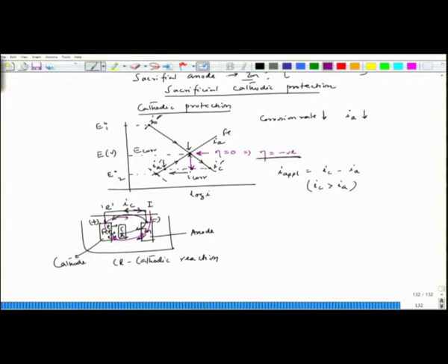Like that way, current will flow like this all the time, and then the entire surface of the metal is protected, and during that time, the zinc surface is actually corroding. So, this is sacrificial anode. Another situation I could have is where I have an iron piece and this is an auxiliary anode, which does not take part in any reaction, rather the anodic reactions take place on this auxiliary anode.